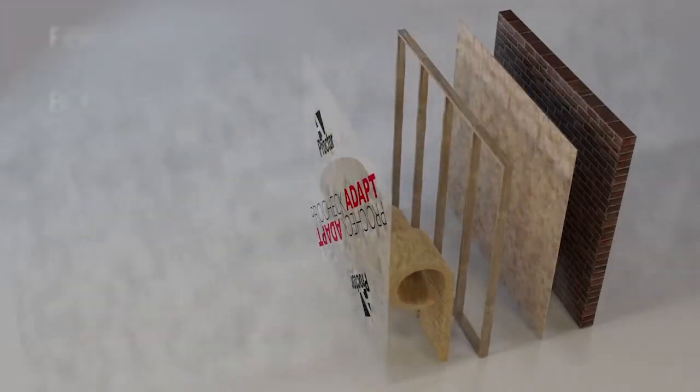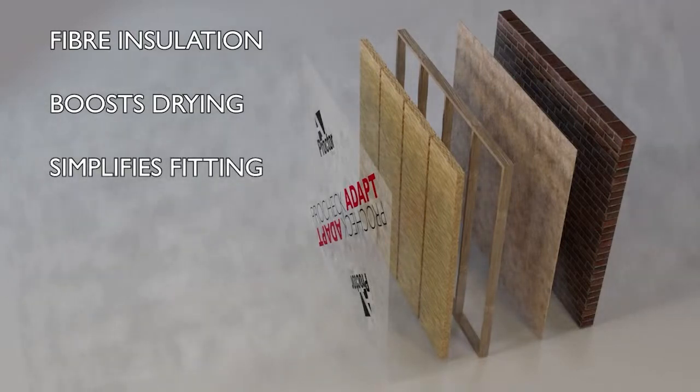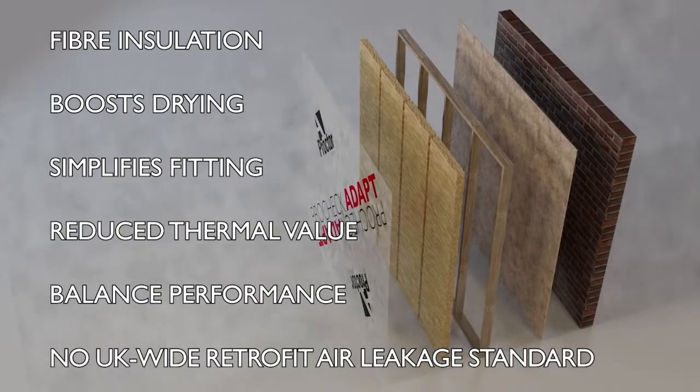This drying process will typically work better if a vapor-permeable insulation such as mineral or natural fibre is used in the framing. Such flexible insulation types can also reduce the likelihood of air gaps between the insulation and the framing, although this does come at the expense of a typically higher thermal conductivity. Depending on the assessment criteria used, this lower conductivity may be offset by the more airtight building envelope a well-sealed air and vapor control layer can provide.